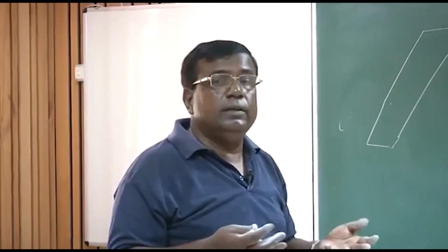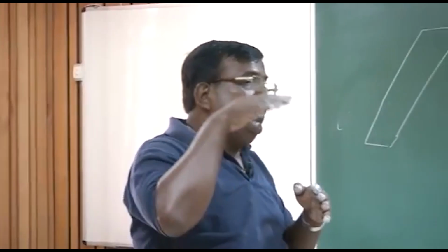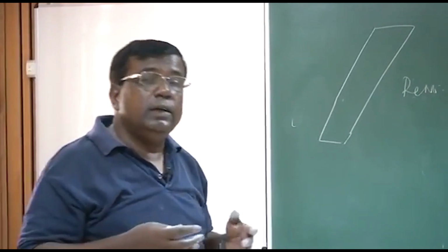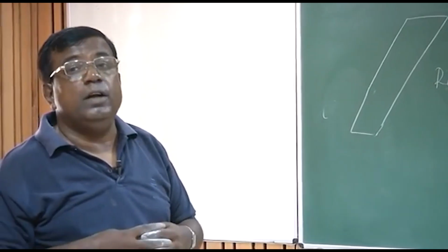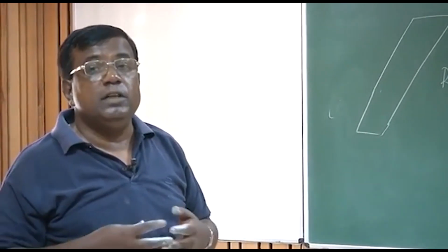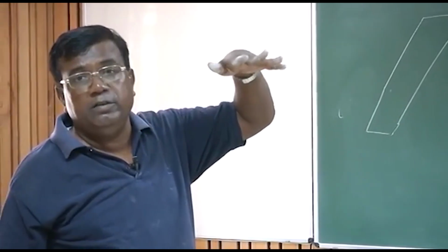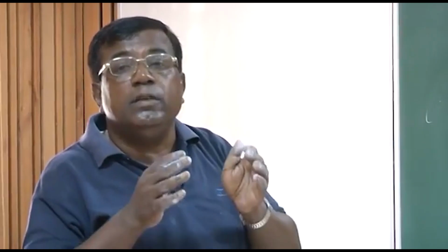So how much advantage it has given. And once I say I am ensuring that the flow in a tunnel has the same Reynolds number, I am actually talking about dynamic similarity. If I am testing for a high speed, then I must ensure that Mach number is the same. That is, whatever Mach number the actual airplane was experiencing, the same Mach number the small model in the tunnel should also experience.